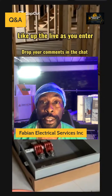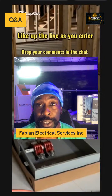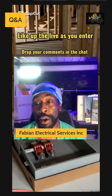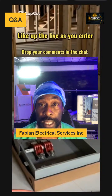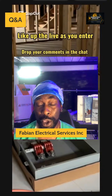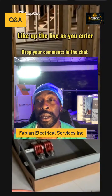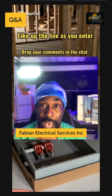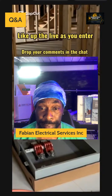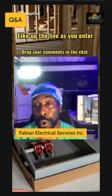You don't want your heat to get trapped inside of the pipe, and that's where your wires will start to melt and so on. So very important when you are pulling conduit, when you are running conduit and so on, and you're strapping it dead front of the home in the sun, the pipe will absorb all of the heat like it's supposed to.